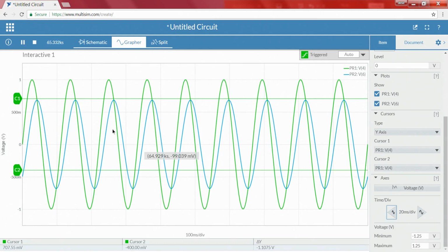If not, try to set our op amp resistor to one particular value and change our resistance values. But if we are really interested in a narrow band of frequencies, one good way is changing the resistance value, and we can observe that there was this drastic change from 44 hertz to 45 hertz itself, and below that particular value it will be completely below the cut-off.